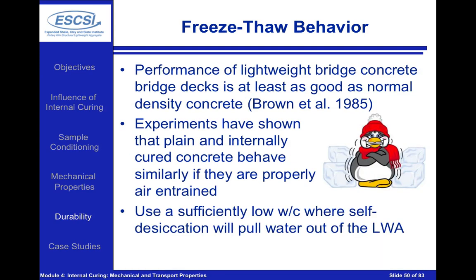So again, to push in a little bit more on the freeze-thaw behavior here, the performance of lightweight bridge deck concretes is at least as good as normal density concretes, and this is from a study from Brown. Experiments have shown that plain and internally cured concrete behave very similarly when they're exposed to freeze-thaw if they're properly air entrained. So the whole idea here is that if you've properly air entrained your concrete, whether it's a plain concrete or an internally cured concrete, that concrete is going to be freeze-thaw resistant.